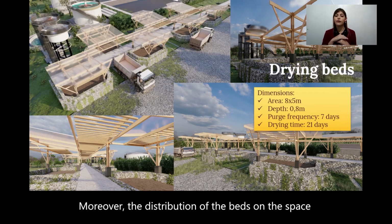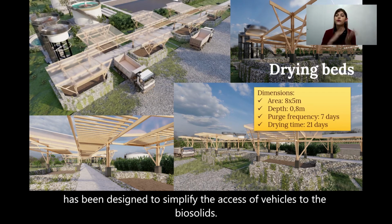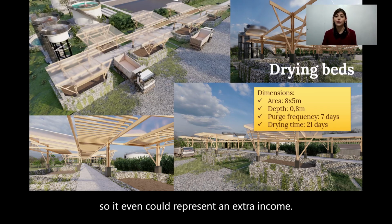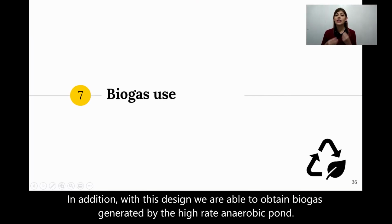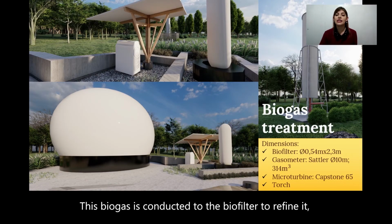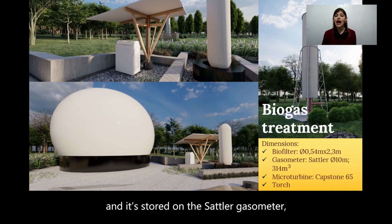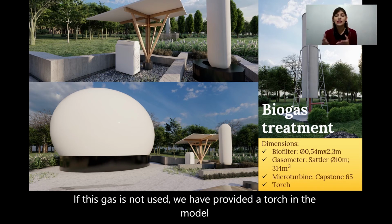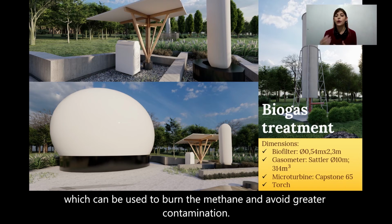Moreover, the distribution of the beds in the space has been designed to simplify the access of the vehicles to the biosolids. These biosolids can be used as compost for the farming region around La Fortuna, so it even could represent an extra income. In addition, with this design, we are able to obtain biogas generated by the high-rate anaerobic pond. This biogas is conducted to the biofilter to refine it, and it is stored in the gasometer. After that, the gas goes to the microturbine to generate energy. If this gas is not used, we have provided a torch in the model which can be used to burn the methane and avoid greater contamination.